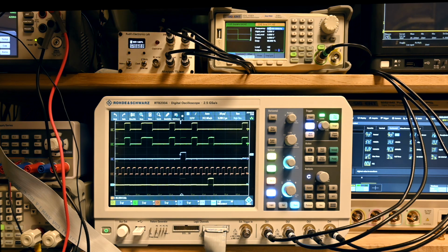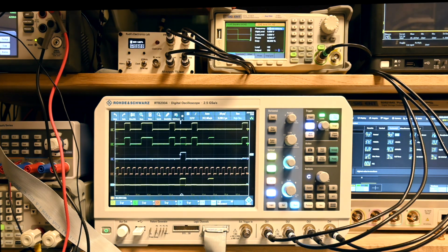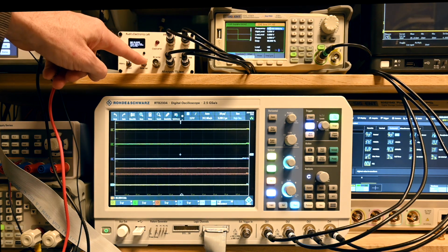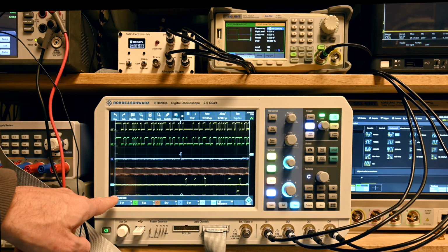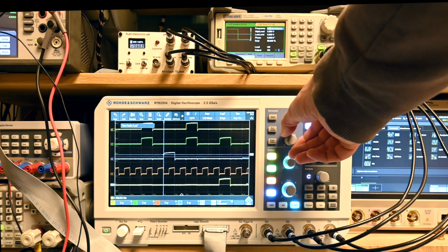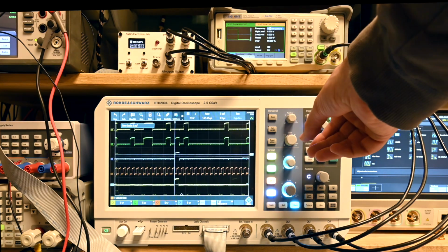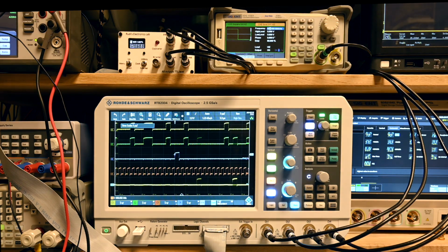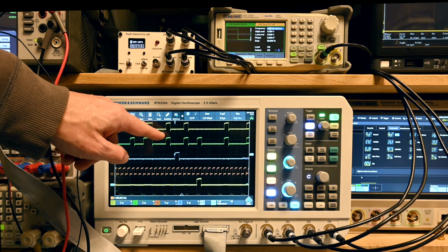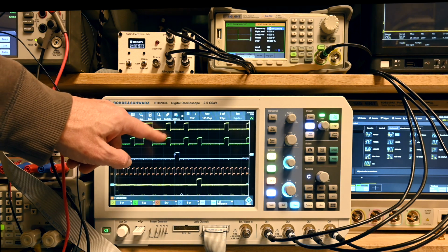I have prepared a signal generator here, and it just creates a square wave signal with TTL properties. So I'll change to the external generator. And we see here the clock signal is now turning to 500 kilohertz. That is what we set this device to. I'll make it a little bit bigger here. And we're still in the scenario where the errors are different per frame. We see a little bit of a slow start here, the slew rate.